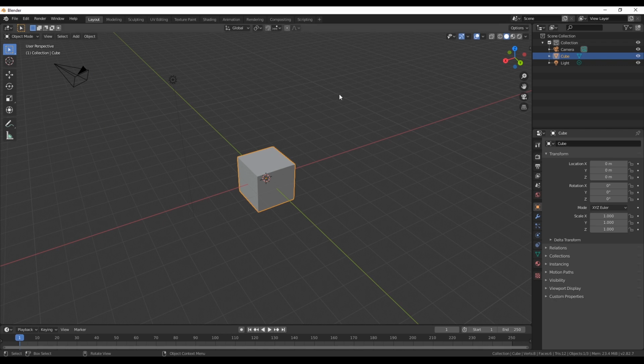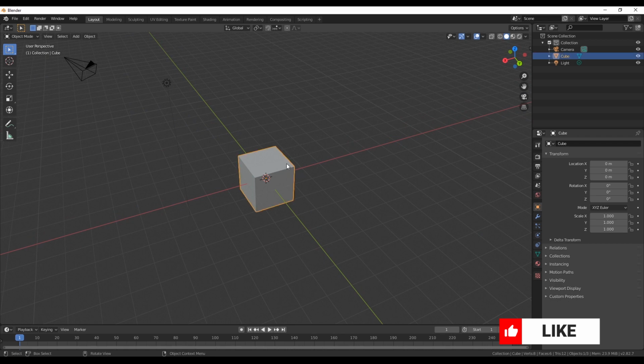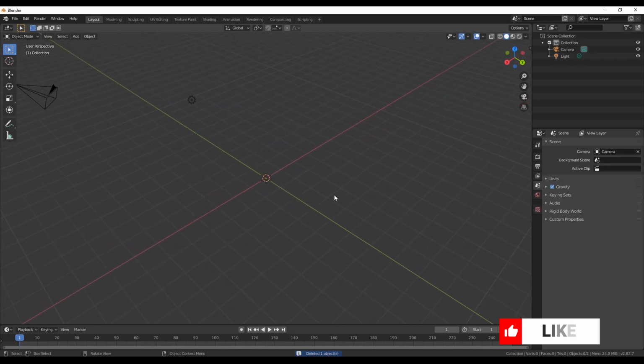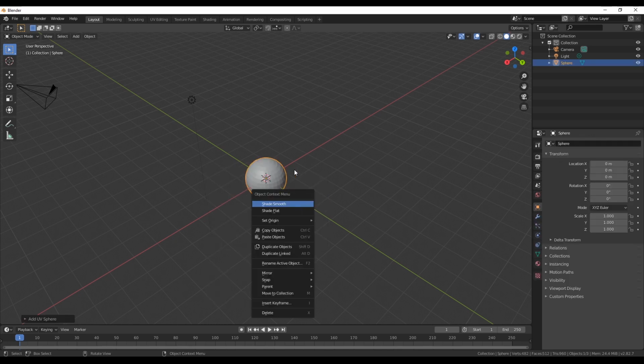So what I'm going to do here is just open up a brand new project, and the project is going to be under layout. Now what you'll notice is that when you middle click, you'll rotate around and you get the default cube. You can delete it. Now we're going to add an object. So the object that I was going to add for the dome is going to be a sphere. So I'll do Shift A, and then I'll bring in, there's different spheres that you can bring in, but I'm going to bring in a UV sphere.